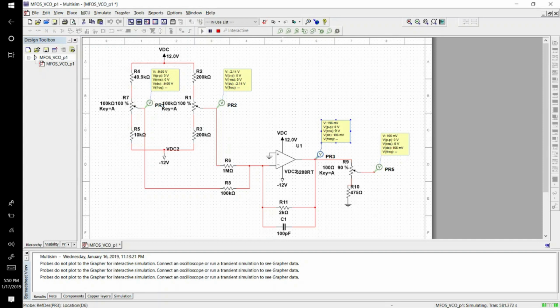Also 9.6, and remember that here it's reading 196 millivolt. So let's change this to 8.6. Okay, so it's at 8.6 and the output is 176 millivolt. So you have 20 millivolt of change at the output per 1 volt of change at the front panel. And this trimming potentiometer here is to lower that ratio to 18 millivolt per 1 volt of change in there.